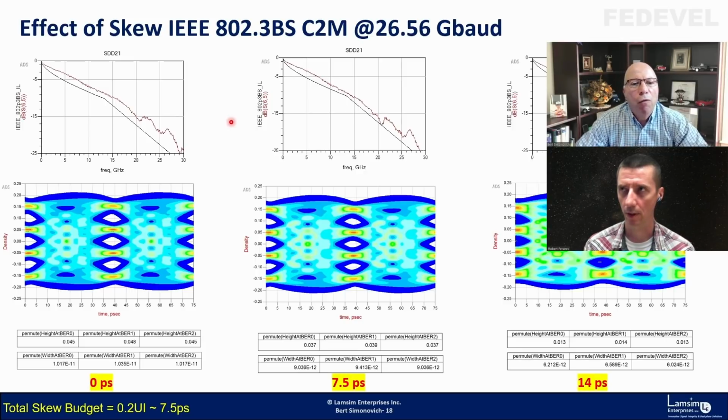So you can also measure the loss of a differential pair signal? A differential pair has 2 traces. So, yes, the VNA probes those 2 traces, at one end and at the other.